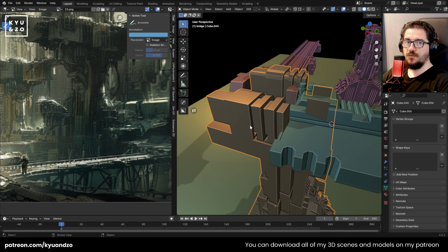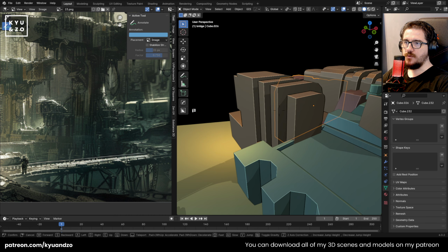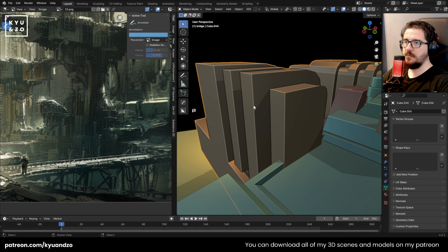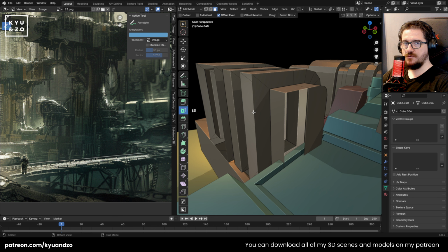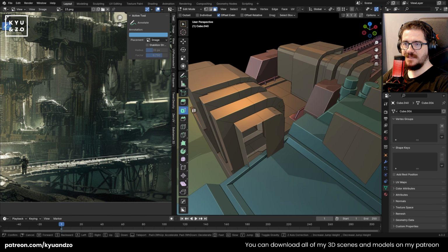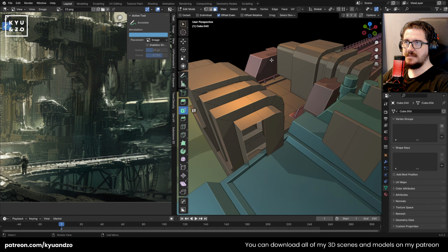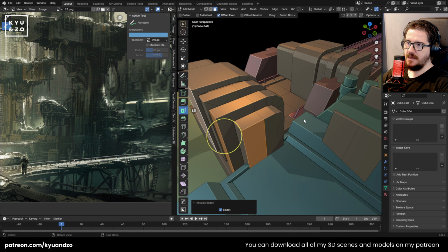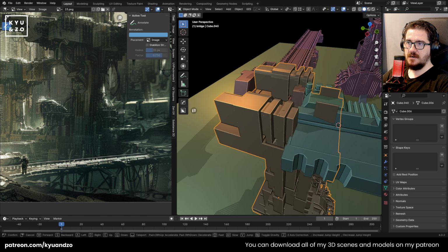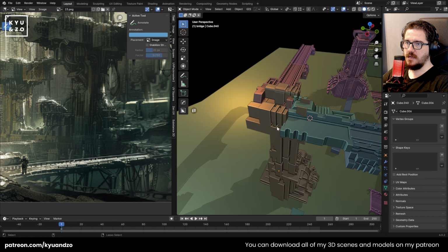Shift H, by the way, let me show you. It's looking normal, right? But if you go into edit mode, you're gonna see these holes, but it's still hiding. It's like a special and private hiding operation, and you gotta fix it in the edit mode of this object. Alt H, and your faces are back. Okay.